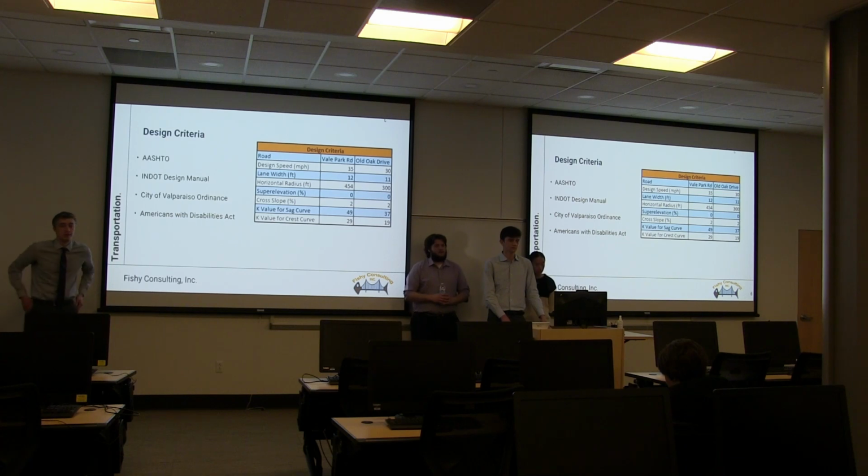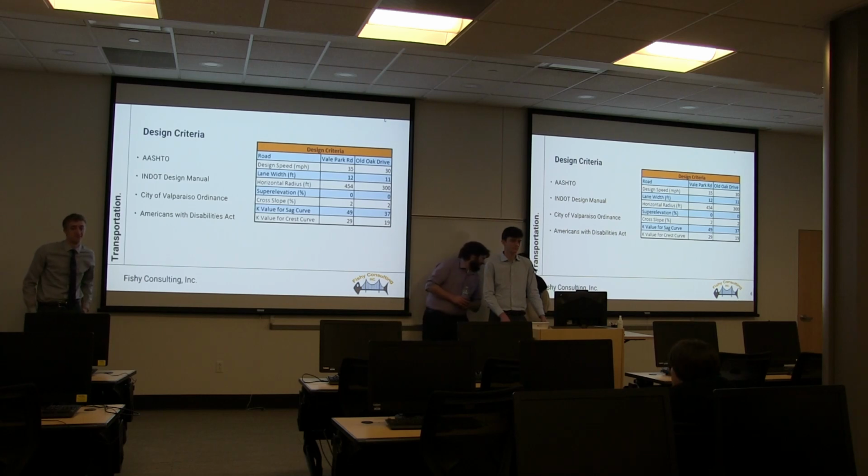I would suggest, because ASCE 7 has a general definition of those risk categories, you might want to consult the International Building Code. In chapter 16, we have very detailed definitions of those. This facility, based on the number of occupants, might fall into category 2, which makes life much easier for you.